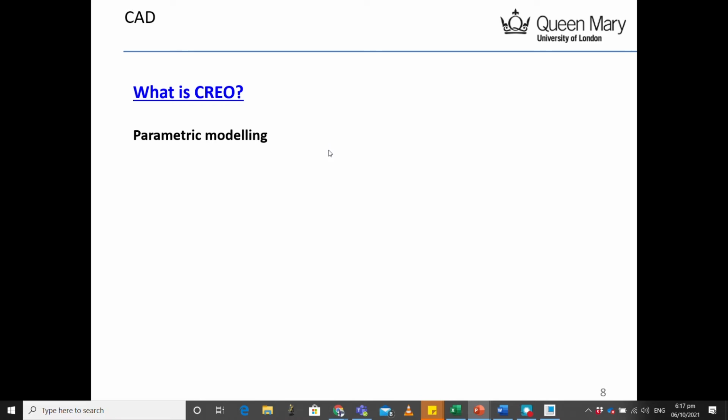So Creo basically works on two basic rules. One of them is parametric modeling, and the other is kinematic modeling. So let's talk about parametric modeling for now. How we work on any CAD software is we build up some parts. Before making parts, we make their drawings, a 2D sketch. Then that 2D sketch converts into a 3D part, and then parts combine to form assemblies. Sketch, part, and then assemblies. And then assemblies can be used with kinematic modeling.